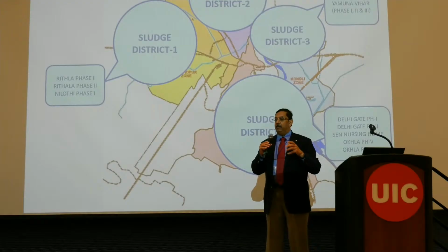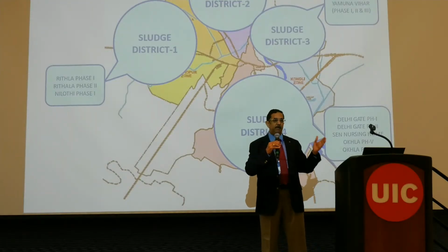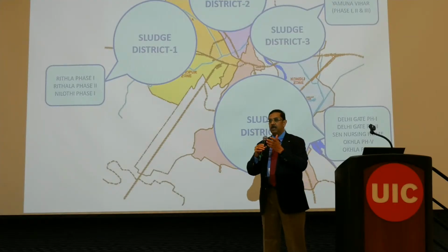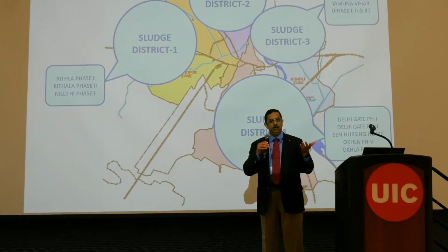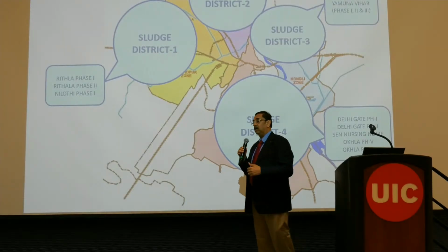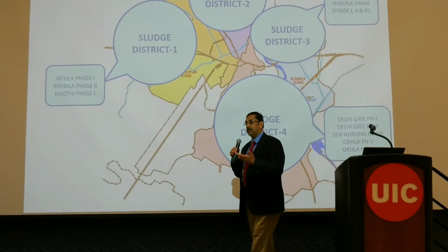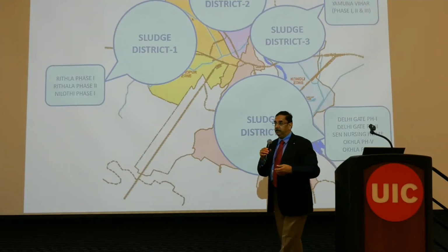Use at the plant. Because understand, not all treatment processes in India presently have the same process stream. Depending upon the regulations when they started, some were for only BOD and SS removal. Some of them have only nitrogen removal along with BOD. Some have nitrogen, phosphorus and the other regulatory requirements.